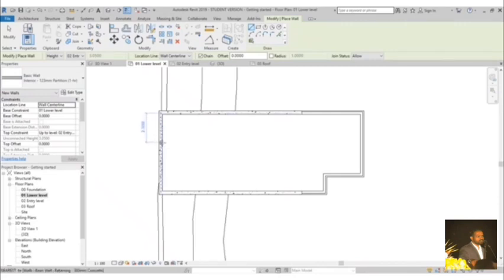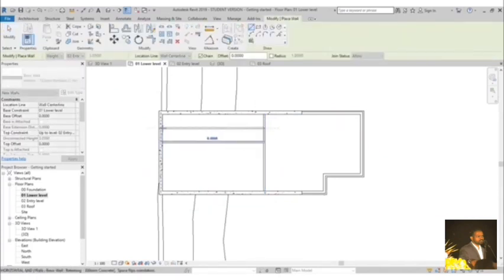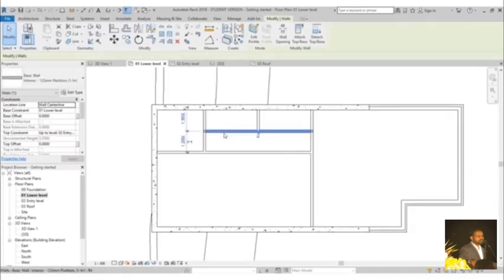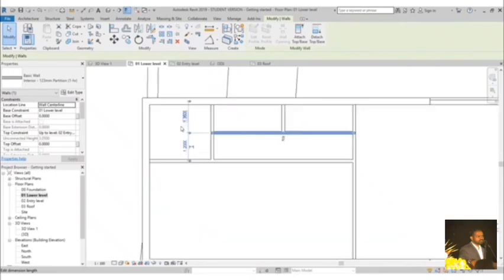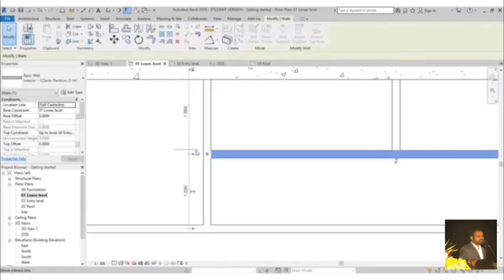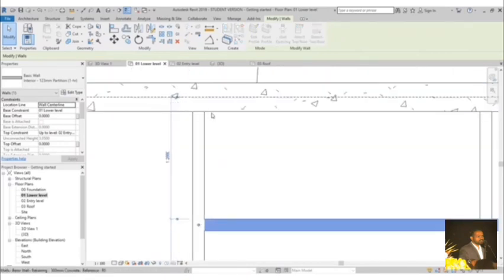And I'm just going to go like this, finish it off over here, extend this to the other side, go to the wall again, do it kind of like this, and then add one room here and one more separation. So for this distance, as you can see, you just select the wall and then you set up the distance or the dimension of the rooms. And if you want to be precise, you can move this little dimension line. So just go from the center to the edge, and here same thing, go from center to the edge.